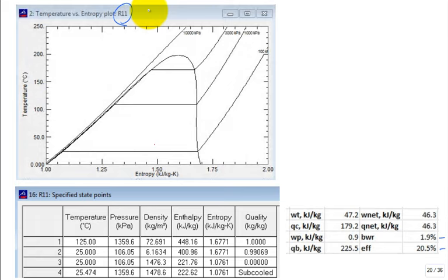It's almost like you have a free heat source and you just want to try and convert as much of it as possible into electricity and sell it. But you're going to be moving a lot of fluid and moving a lot of heat transfer and not getting as much conversion over into electricity or shaft power. So the back work ratio? We would like it as low as possible because the back work ratio is how much of the turbine output had to go back and feed the pump. Yeah, we would like that as low as possible.